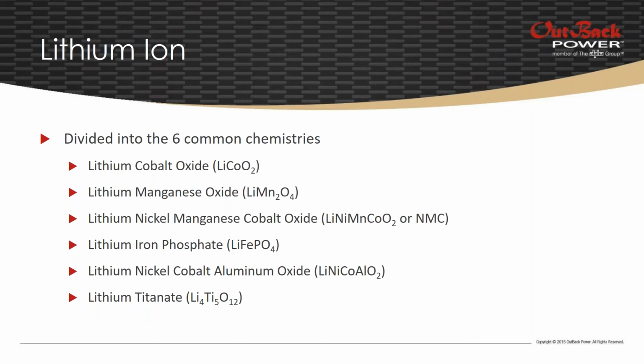So all of these chemistries also have an extremely high cycle life. Many of the spec sheets that I've seen are in the 8 to 10,000 range, sometimes more. So 8,000 cycles as compared to a lead acid battery, which is over 1,000. And they can also discharge up to 100% of their capacity without permanently damaging the battery.